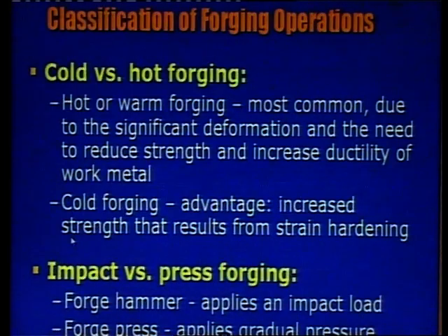So you can have cold forging or hot forging. Hot forging is when you heat the component or raw material. It is most common because you can have significant deformations with a lesser capacity of the press. Whereas in cold forging, you do not heat the component.